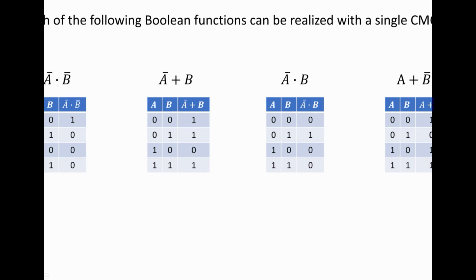So if you look at the rows of the table where the inputs are zeros, then the output cannot be 0, right? So that's a problem on this one, right? Because A is 0 and B is 0. That would turn off all the NMOS transistors. And since the NMOS transistors are responsible for setting the output to 0, how can the output be 0? The output can't be 0 if you don't have any NMOSs that are turned on.